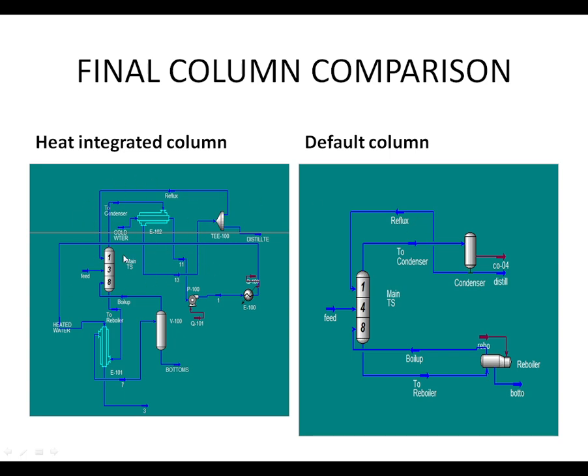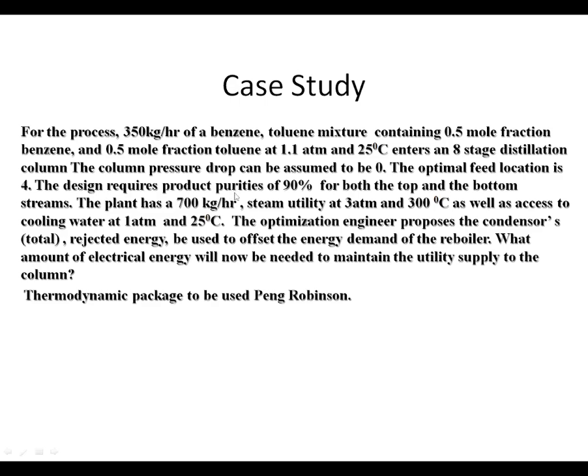more of a real life operation. So we have a heat exchanger instead of an electric cooling condenser, an electric cooler, or a kettle reboiler. So we're going to use the cold stream, then we're going to cool our condenser stream, then we're going to pump, and then have an external electric boiler to raise that temperature to maintain the utility stream that will be supplied to the reboiler. So this is actually the case study, so you can understand that.